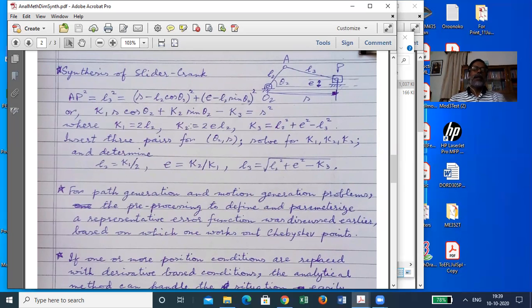The reason is that one linear dimension is involved in the variable itself, which you are actually supplying. Earlier both were theta 2, theta 4, so dimensionless quantities were supplied, both of them. Now one is dimensionless, theta 2, but the other has a linear dimension. So depending upon what comes in the coefficients, K1, K2, K3 may have different dimensions. All of them will not be ratios.